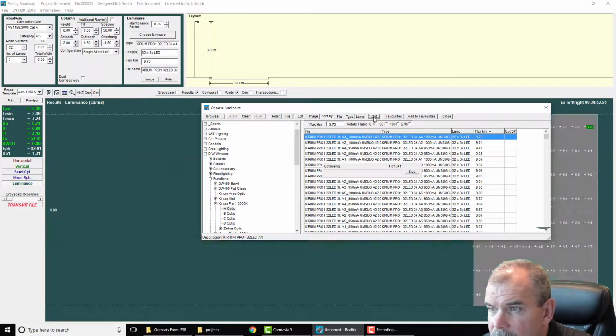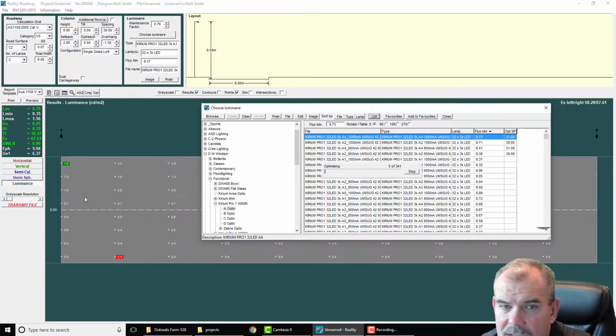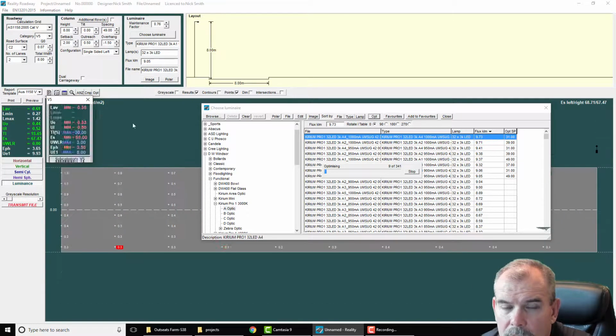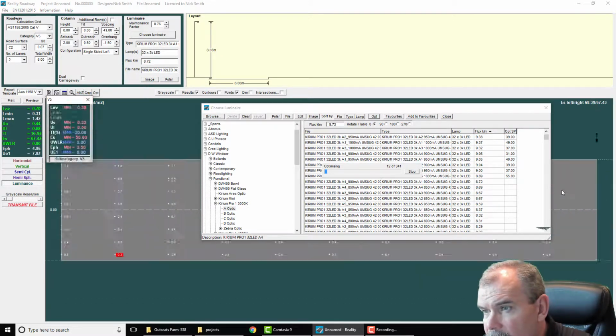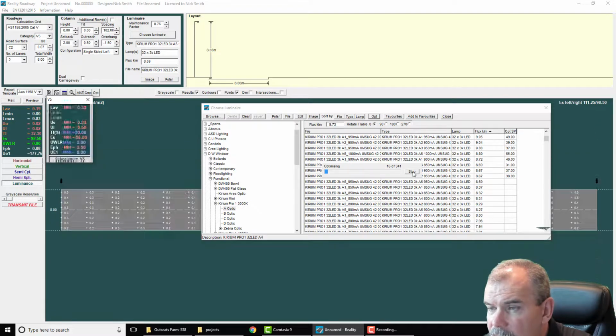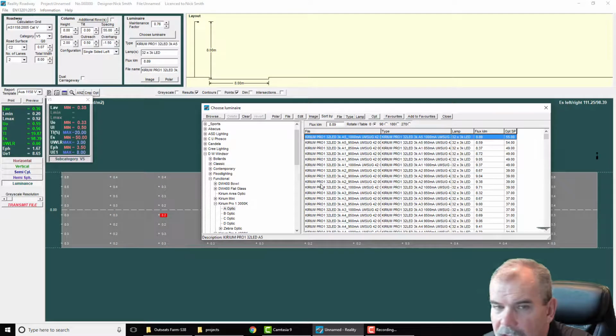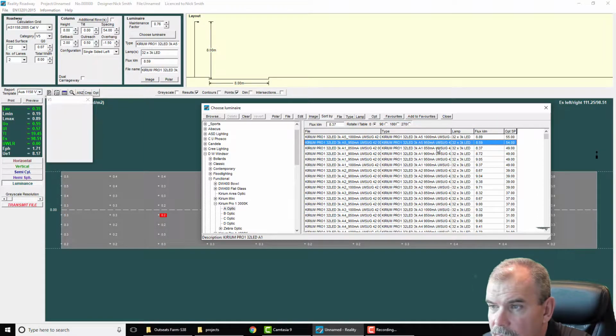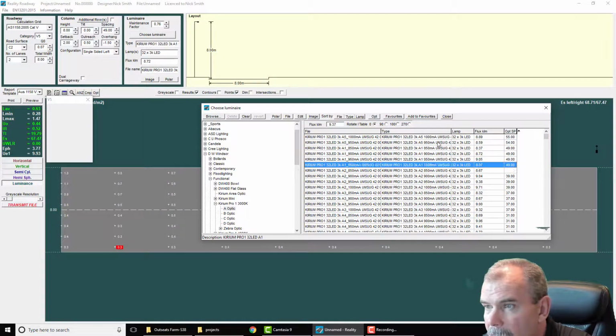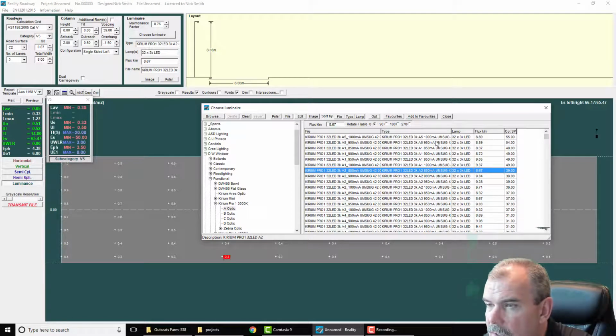And then we can go through the same process. What we're now calculating is luminance, and those are the target figures we're aiming for, exactly the same as before. We can press stop at any time, and that will allow us to select the highest spacing and determine a solution that works best for us. It may be you want the best spacing, or you already have an existing solution and want to look at what spacing and which optic is going to work best for that particular requirement.